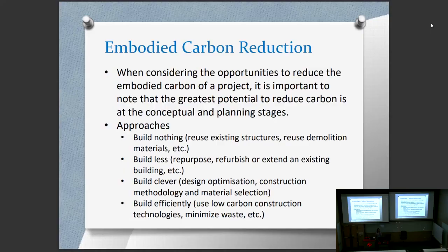So choose the low carbon material, or the material with higher recycled content, and maybe the construction methodology will allow you to extract the material for reuse at the end of the building life. Build efficiently: use low carbon construction technologies, minimize the wastage, simple design so as to reduce the material wastage. So all these are approaches to reduce the embodied carbon.